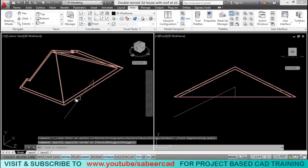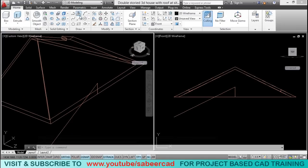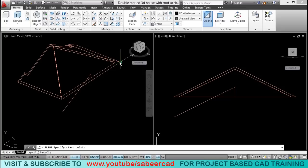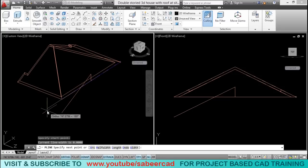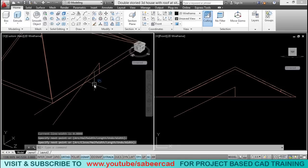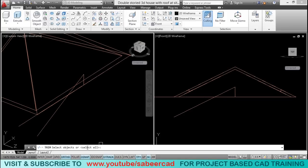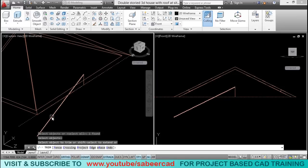Now I have to just cut off this excess portion. Okay, so I'll go to Polyline and I'll start a polyline from this endpoint to this endpoint. You can just pick a point somewhere over here. And this line will act as a cutting edge to trim this excess portion. So I'll click on the trim command. When I'm asked to select objects, I'll choose this particular edge as a cutting edge, give an enter, and when you're asked to select the object to trim, you can just click on this.